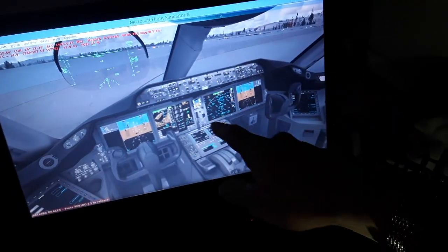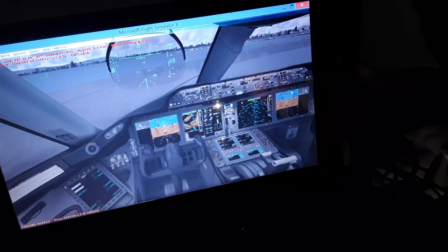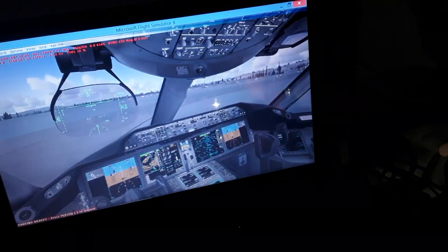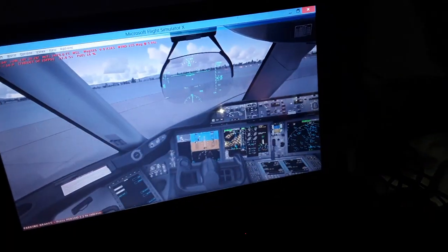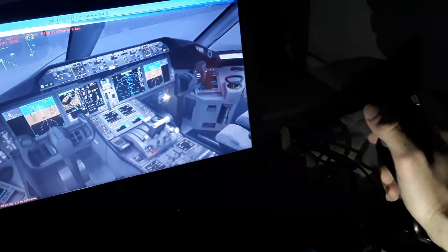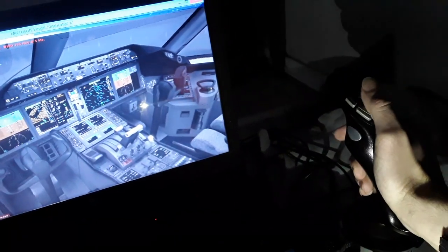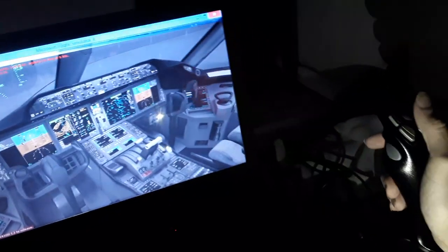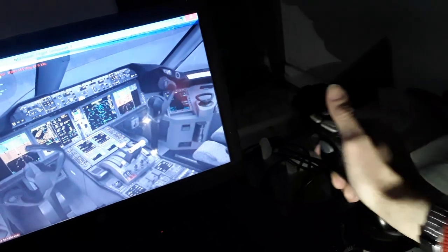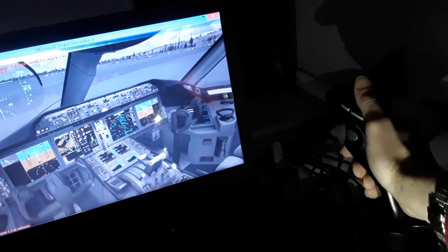You control the nose wheel in the front of the aircraft to make turns, like 76 degrees, and it's decreasing as you increase airspeed for takeoff, like 7 degrees above 40 knots, and then 0 at like 70 knots. You have the rudder aerodynamically effective at like 45 knots. So you will see the controls. You can see both sides are interconnected, the captain and the first officer. They move together. They're not like the Airbus, where you have the side stick priority, unless you have a failure.